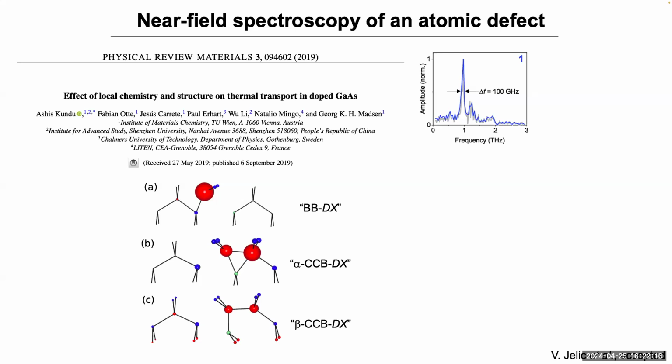And there's a particular thing in gallium arsenide that's been postulated but hadn't been seen directly called a DX center. This corresponds to a donor vacancy complex. So what it means is you have a silicon replacing a gallium, and then you have an empty gallium site, and they form a complex. Now, within gallium arsenide, that's not so energetically stable. But remember, we had this sort of low potential area where we were looking. So you can basically find regions where it's stabilized at the surface, even though maybe it wouldn't be without those other defects happening.